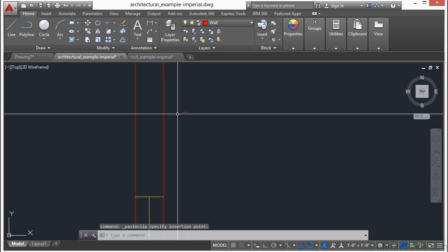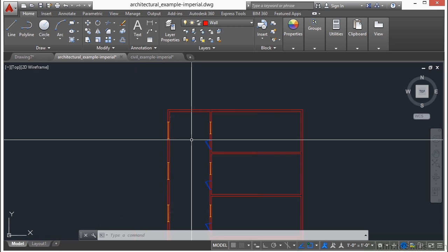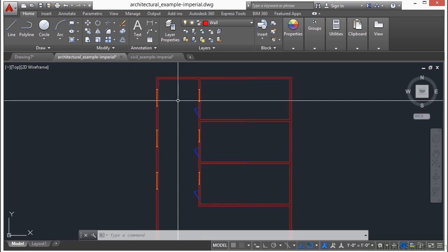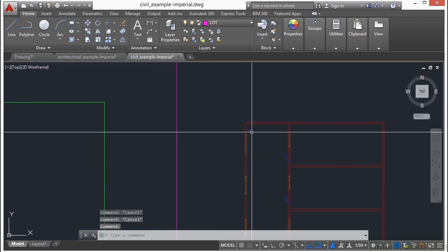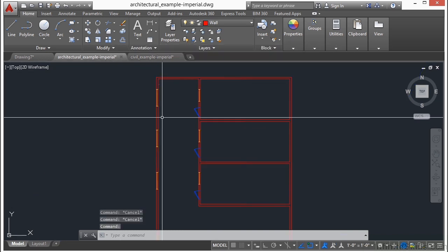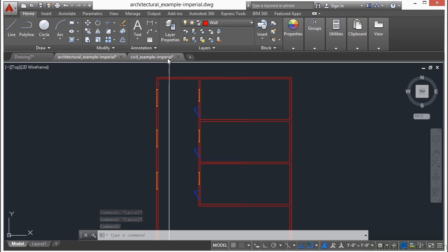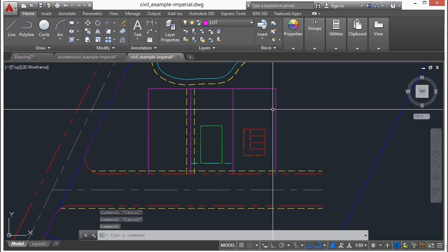We see it's much smaller. Very much smaller. Because in this drawing file, AutoCAD sees 1 unit as being 1 inch. So that kind of gives you an idea. But when I'm using the reference files, then AutoCAD says, hey, look, this drawing, my main drawing that I'm in, the civil example drawing, is drawn in at feet for units. And the file I referenced is drawn in as inches. Oh, that's a scale factor of 12. I need to scale this for them so everything is drawn correctly in real world lengths in units. And so it knows that.